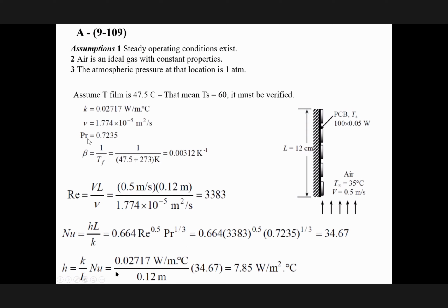And then we can calculate here. I can find the heat transfer coefficient here. But at this moment, I should stop here and say this is my Reynolds number and go back and calculate the Grashof number, okay? Therefore, now we calculate this assuming it is only forced convection, and I have this value of heat transfer rate, okay? Then I can go back. Any question, please?